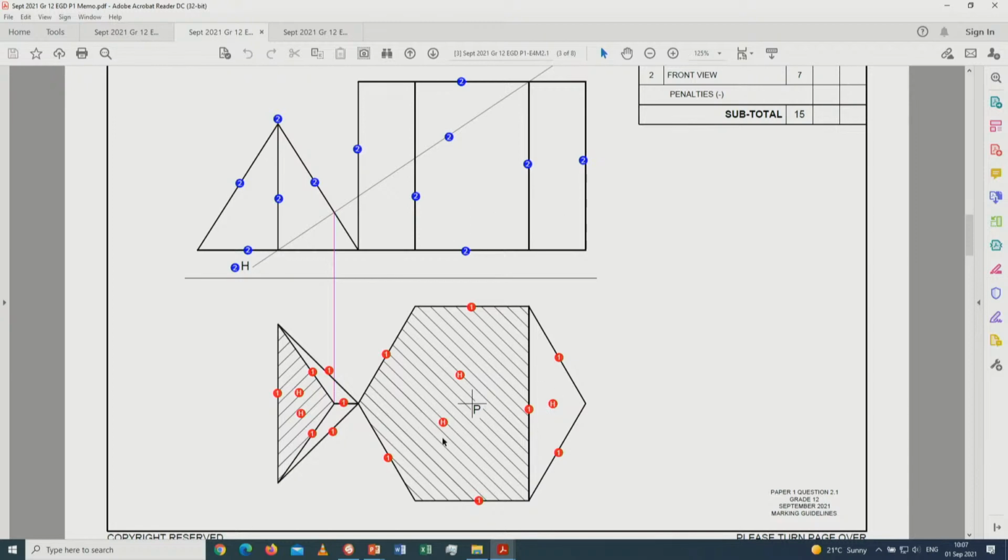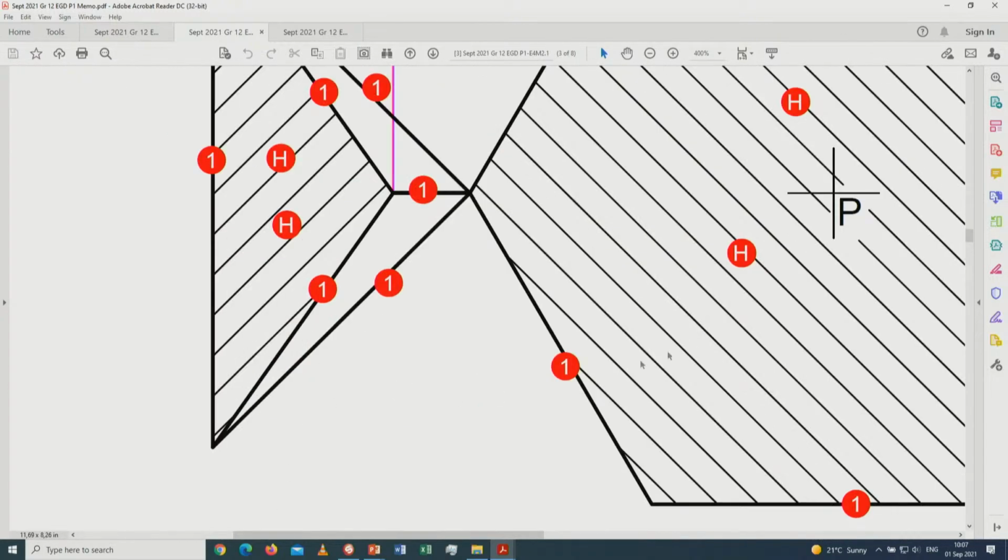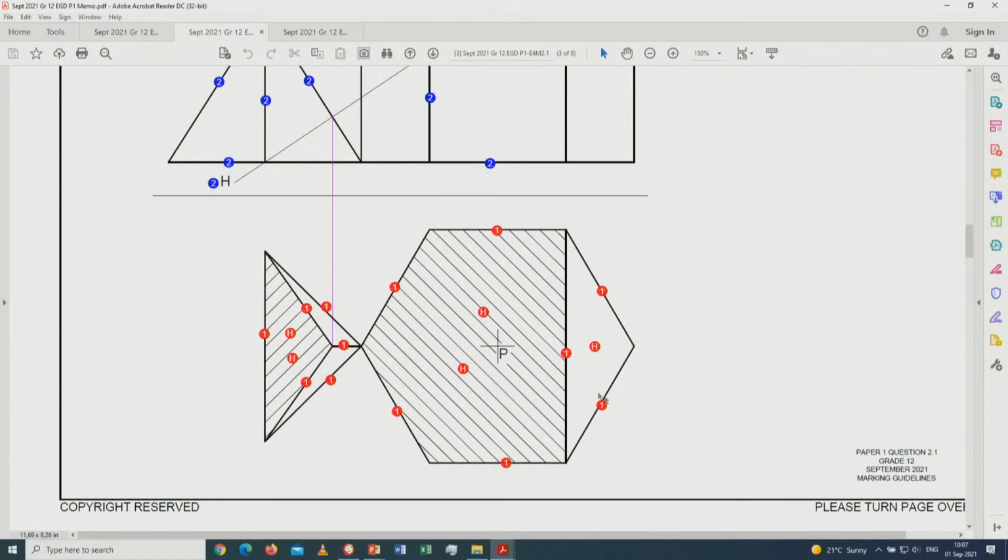And then the next is basically SANS compliant. In other words, it's not to say that hatching is a compulsory 45 degrees. So this hatching can be on 60 degrees, right? But at all times, the spacing between the lines must be SANS compliant. The type B quality that you get for these lines should be the SANS compliance part of it.